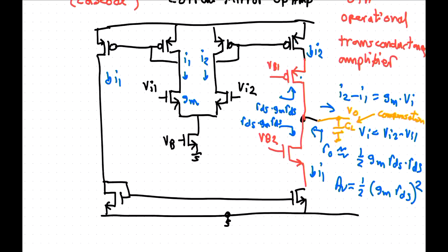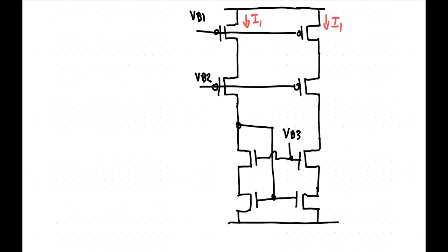So I have made a small variation of this circuit here. We've got a cascode current mirror here, and then we have something at the top that I have also made into cascode, but I have not made these connections and made this a bias point instead. So we have a circuit which now looks like this.